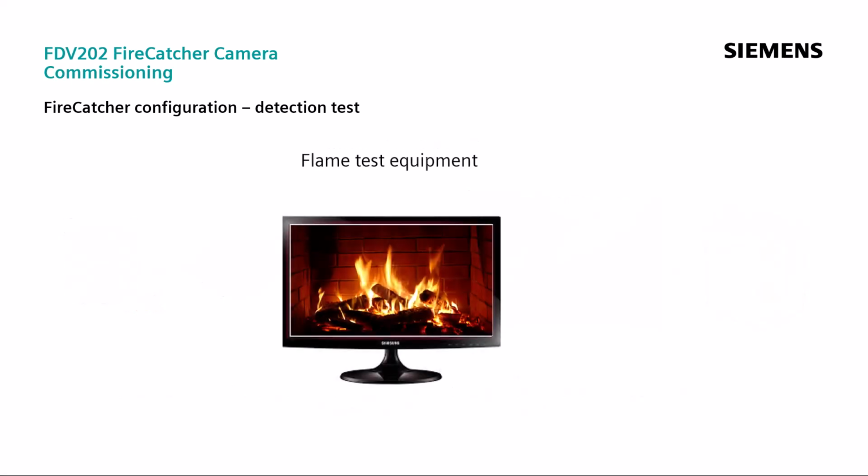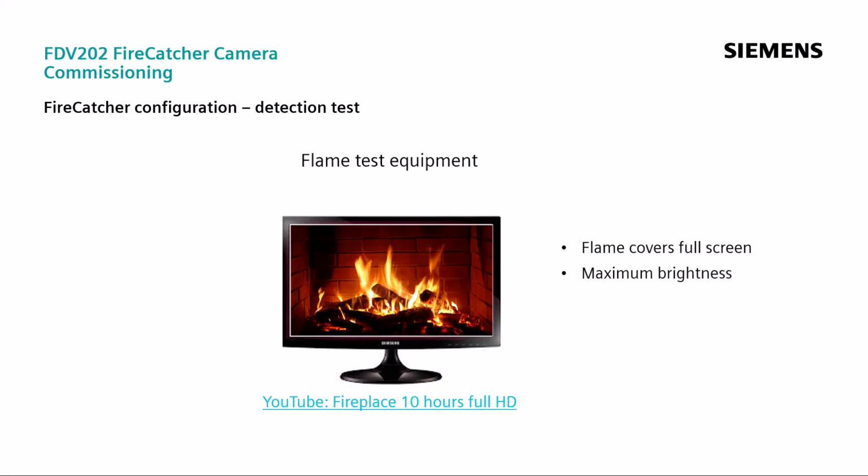Testing the detection of flames should be done by means of flame videos. These videos are available, for example, on YouTube. Please pay attention to the following aspects. The flame covers the full screen, the screen is set to maximum brightness, and the screen's position is perpendicular to the camera.